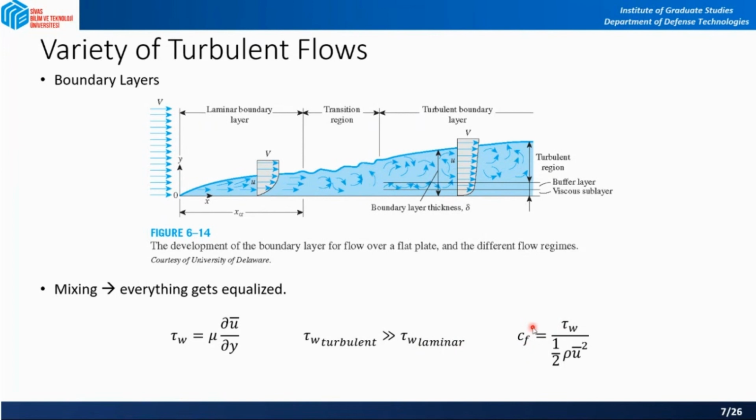Therefore, you can see why in laminar flows you can have much reduced resistance compared to turbulent flow. In external aerodynamics as well, for example, when you want to minimize the drag on a wing, you need to know the boundary layer characteristics and the wall shear stress on an aircraft wing. This changes in laminar and turbulent regions, so both of them can exist on the wing.